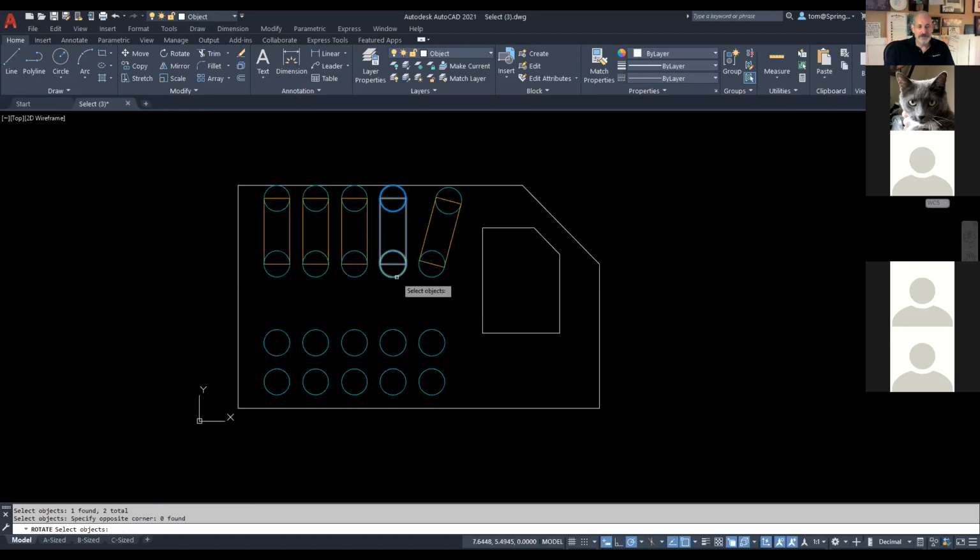And once I've selected them all, I right-click my mouse. My base point's going to be here. Click on the base point, verify that it's actually asking me for the point, and I type in 3, 4, 5, and hit enter. And this is how I go ahead and do this. I'm just going to continue on this, and using any other tools that I know, I can put these into the proper rotation, just like I'm doing here.